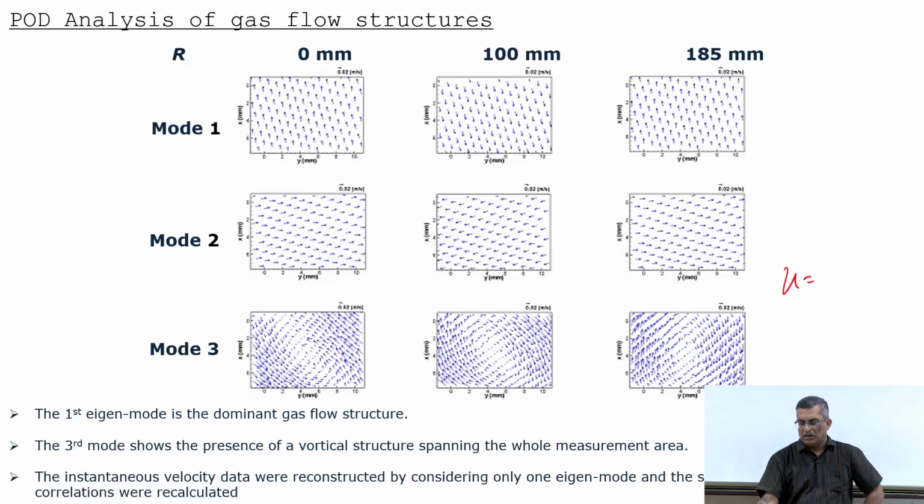According to Reynolds decomposition, this is mean plus fluctuations. But we know that when we say U dash, this itself contains a spectrum of turbulent eddies. So out of those, the small scale eddies are homogeneous and they are isotropic basically. They have similar behavior. So that is why they are random in nature. However, the large scale eddies are anisotropic. Okay. So they represent the flow structures in your flow.